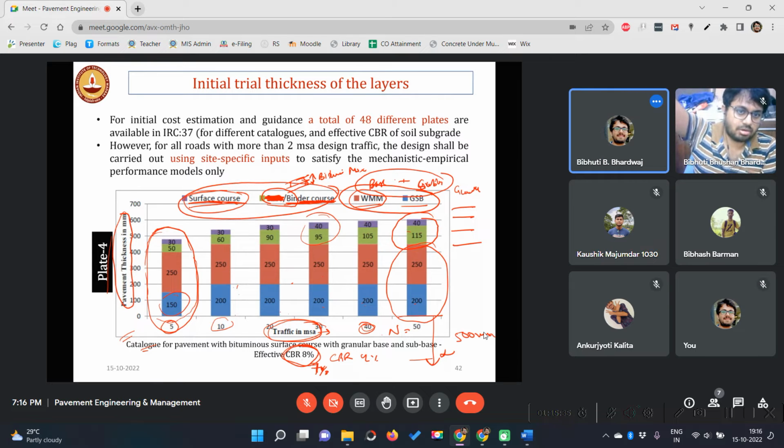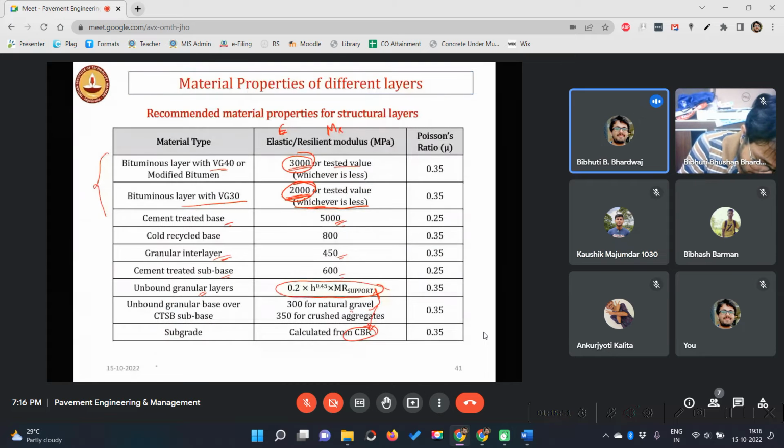When it is more thicker, then, you know, like this. Earlier, okay, you see, say here CBR is 7%. Here CBR is say 9%. Okay, so in 9%, if I provide this much thick pavement, you know the load is distributed like this.